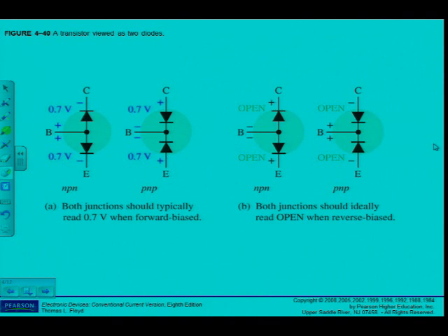And the other thing is, of course, some of the multimeters have a setting for HFE where I can measure the beta. Then you should also know what the beta more or less should be, and if I get the correct beta reading or in the range, because I know it's not a set value, it's a more or less value, then I also know that the transistor operates.